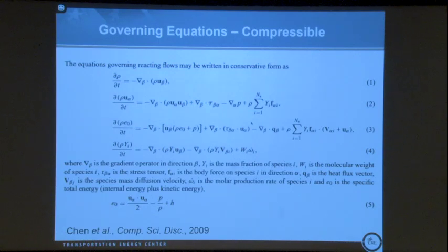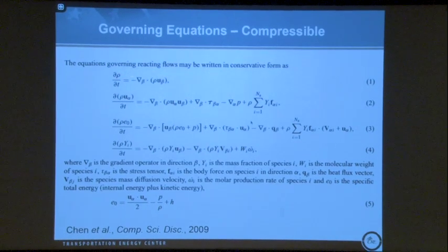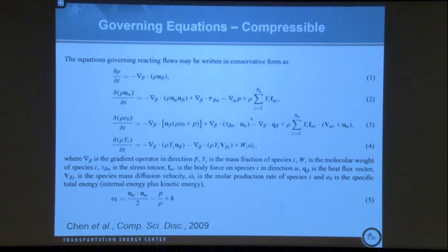The governing equations that we solve, for example, in a compressible solver that I've written, include the conservation equations for mass, for density, momentum in 3 directions, the total energy, and the species continuity equations, conserving the species, where the total energy here is the sum of the internal energy, shown here, and the internal energy on the right, these right 2 terms, and the kinetic energy shown here.